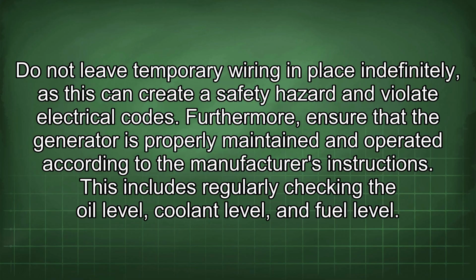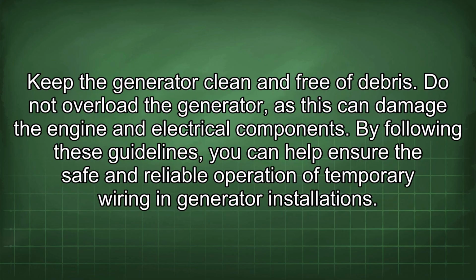Furthermore, ensure that the generator is properly maintained and operated according to the manufacturer's instructions. This includes regularly checking the oil level, coolant level, and fuel level. Keep the generator clean and free of debris. Do not overload the generator, as this can damage the engine and electrical components.